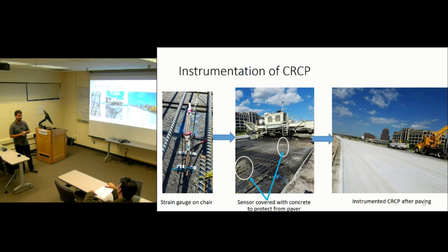It might happen, but when there is an approach slab, there is an expansion joint over there, which allows movement of the CRCP. So we don't usually see a lot of cracks near the approach slab. A lot of CRCP is mostly restrained in the middle portion. In the portion where there is expansion and contraction, we usually do not see a lot of cracks within about 100 feet of the expansion joint. So it usually occurs in the middle, until and unless we have some problems with erosion where the base erodes.